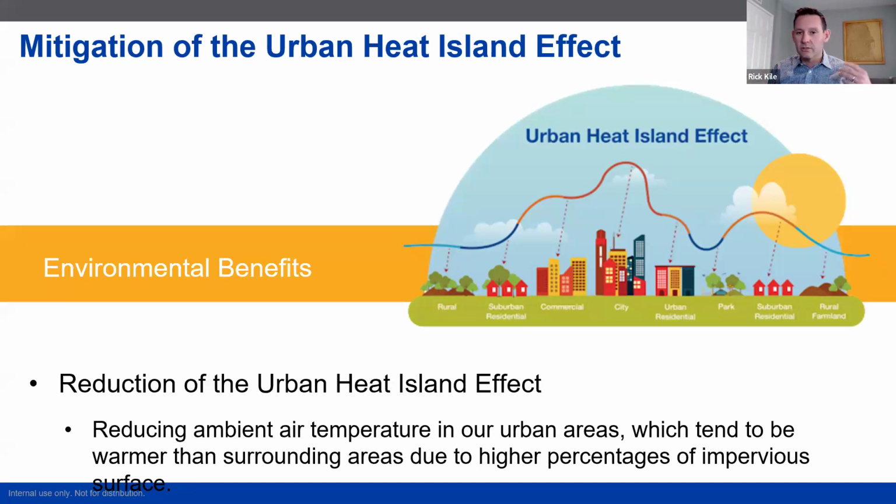The surface temperature of an extensive vegetated roof, something planted with sedums, which we'll review in a little bit, on a hot summer day is in the low 80s, like 82, 85 degrees. That's largely due to the plants, the evapotranspiration processes involved. It's much cooler. A dark colored roof on the same summer day is 130, 140 degrees. So there's a pretty big temperature swing at the surface.